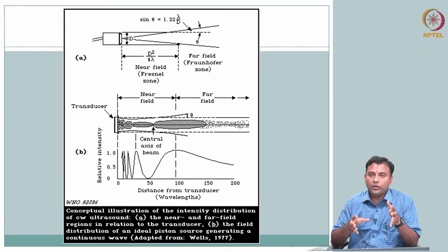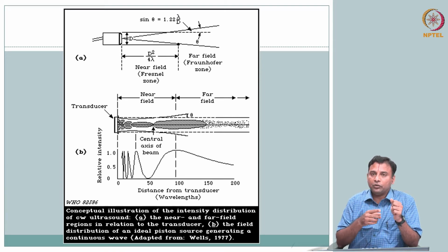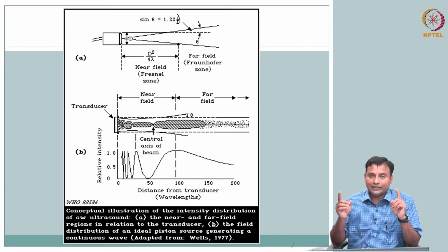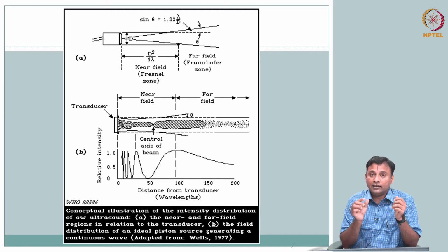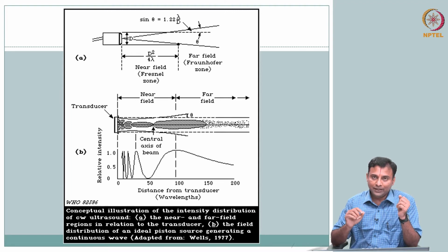Okay. And so, now we are at a stage where we understand that we can use a transducer and give harmonic excitation, and that could give you a pressure wave. So, the challenge that we are now going to address is, what is the shape of this pulse, what is the shape of this waveform. I excite a transducer, and the frequency is dependent on the thickness, that is what we saw. The thickness of the crystal determines the resonant frequency, but then we also want to know why there are different sizes and shapes of transducer, right.